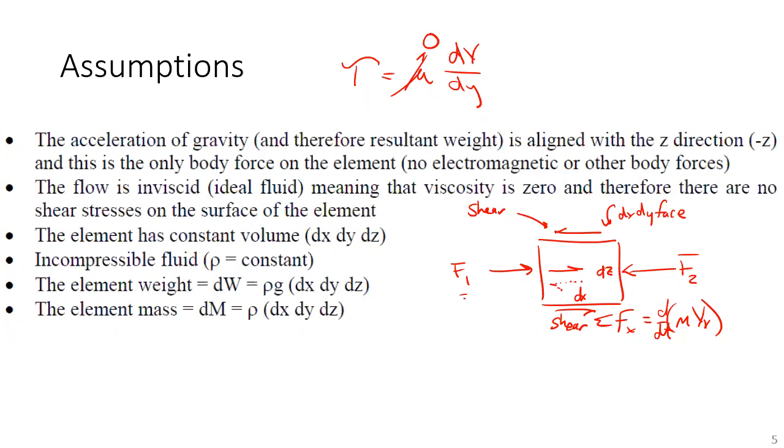We're going to assume that we have an incompressible fluid, that the density is constant. Obviously, that tailors this derivation towards liquids. Most liquids we can assume to be incompressible. Gases at low velocities also somewhat satisfy this. So again, the movement of the air through the ductwork in this building is almost a constant pressure system. It only changes once you get close to the pumps that are moving the air around.